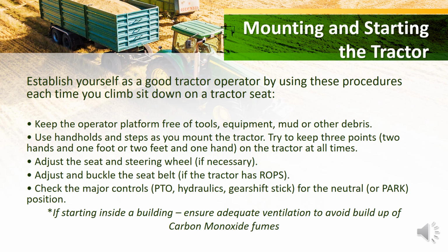Adjust your seat and steering wheel if necessary. So if you weren't the last one to drive that particular vehicle, make sure that your seat is in the position you want it to be in, your steering wheel is in the position you want it, and you don't want to be adjusting these while you're driving. Adjust and buckle the seatbelt. Also, make sure your major controls are in the neutral position. Your PTO, your hydraulics, your gear shift, they should all be in the neutral position. If you're starting inside a building, also make sure that you have adequate ventilation so you don't build up carbon monoxide fumes.